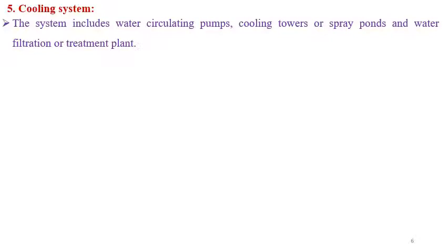Obviously at such high temperature the metal will lose its characteristics, and the piston will expand considerably and seize the liner. So we need an essential external cooling system. This system includes water circulating pumps, cooling towers or spray ponds, and water filtration or treatment plant.